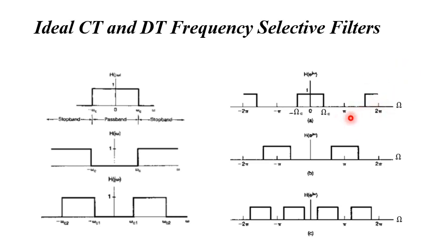If you recall, we said that discrete time signals cannot have frequencies greater than minus pi or plus pi. When we increase the frequency of the discrete time signals, it increases from 0 up to pi. So the maximum frequency they can have is pi.